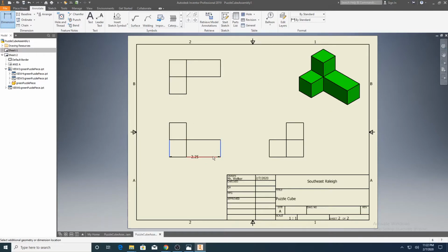So remember, under the dimensioning rules, we should have the overall width shown. Ideally, the dimensions will be between the different sketches. We need to include enough information that we have it fully drawn out, so we can at least calculate unknown values. We can use the different views to help us piece the information together. And we can go by some of the suggested distances, but not necessary for some cases. So in this case, we've got the width, the height, and then we'll include some depth information.